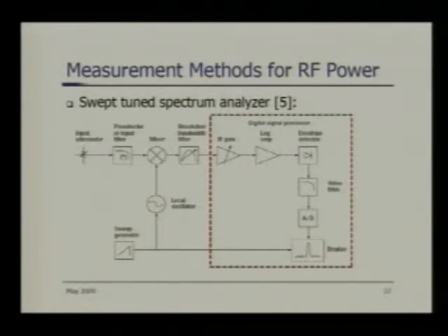Then there is a bandpass filter to band limit the signal. This is really the down conversion unit, the down conversion mixer. It goes to the resolution bandwidth waveform. I believe that most of it is familiar to you, as you have used the spectrum analyzer. Now, from that point on, it goes to the